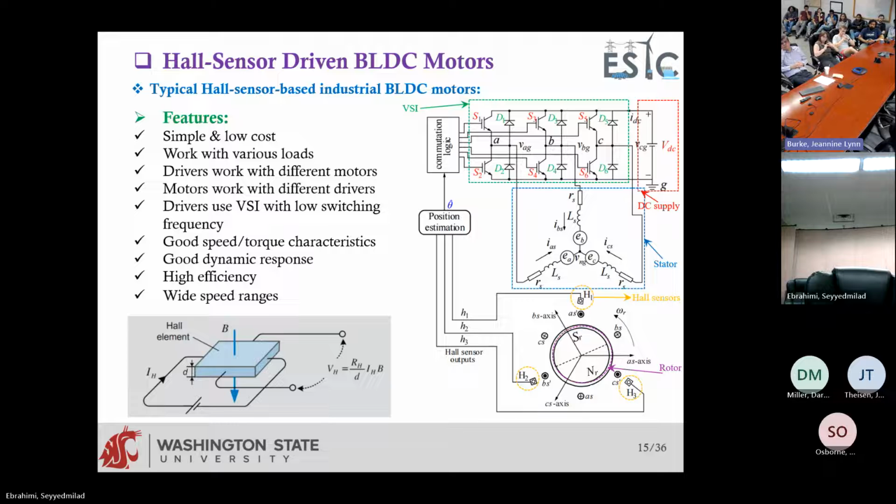Lorentz force. Then depending on whether the magnetic field is this way or that way, those positive or negative charges will either go to this side of the Hall element and negatives here, or positives here, negatives here. Based on that, the voltage that you get from this side of the Hall element will be either positive or negative. So you can have a logic that if I get a positive voltage, it means that the magnetic field was this.